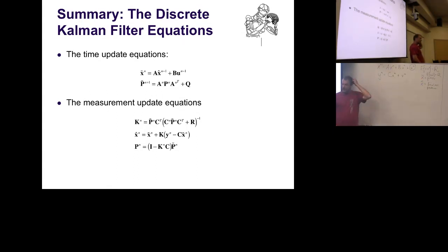Well, this here is measurement noise. You could measure measurement noise by simply having your robot system running in a steady state, and measuring the same state again and again, and then computing the covariance matrix of it, or the variance, whatever it is, multidimensional or not. Okay? So that would literally be what I showed you before.